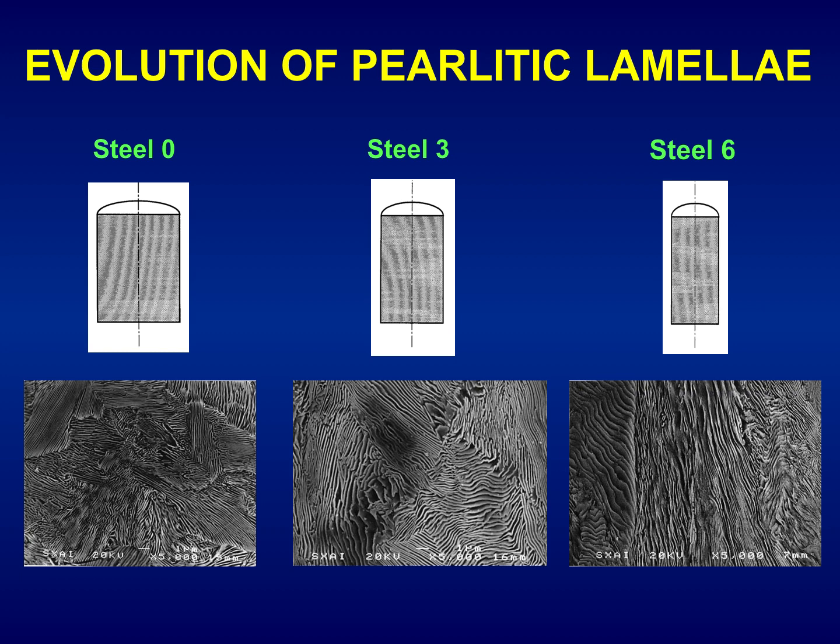It's a microcomposite with lamella, it's like a laminate with the lamella oriented in the vertical direction of the micrograph, that is, in the direction of cold drawing y-axis.